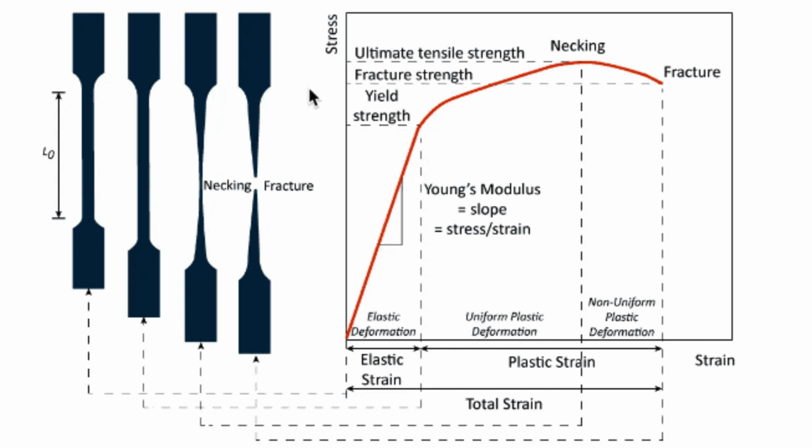Here the material is undergoing a rearrangement of its internal molecular or microscopic structure, in which atoms are being moved to new equilibrium positions. This plasticity requires a mechanism for molecular mobility, which in crystalline materials can arise from dislocation motion. Materials lacking this mobility, for instance by having internal microstructures that block dislocation motion, are usually brittle rather than ductile. The stress-strain curves for brittle materials are typically linear over their full range of strain, eventually terminating in fracture